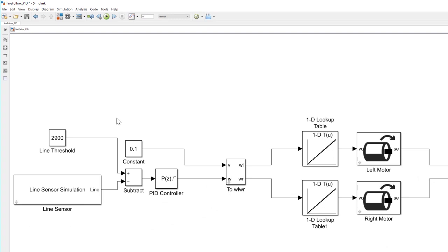For line following applications, it is a popular method to use a PD controller instead of just a P controller to get a quicker response to detecting lines. Recall that D controllers are very sensitive to noise, so start with a very small value to test if that controller works. Let's set the D gain to 1e-5, which is a small value equal to 10 raised to minus 5.